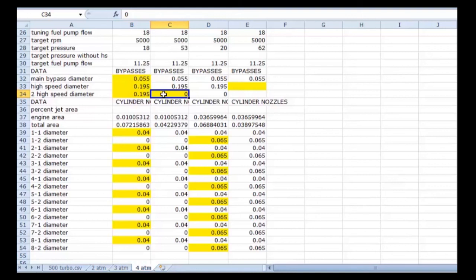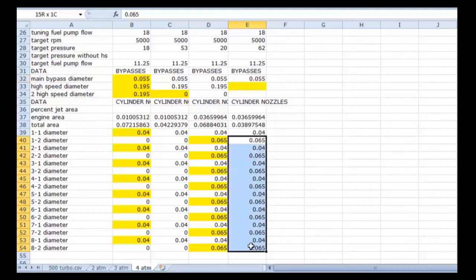In the next stage, we bring in additional nozzles, so for 2 full rows of nozzles, and that gives us the next stage of enrichment. And then the final stage, we drop out the last additional bypass, and we're running on strictly a main bypass and 2 rows of nozzles, and everything's been adjusted for the 3-to-1 air-to-fuel ratio goal that we wanted.